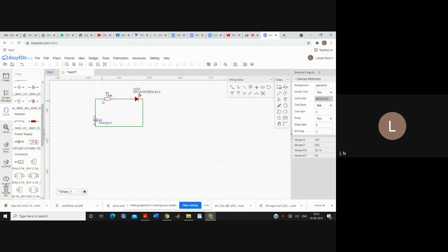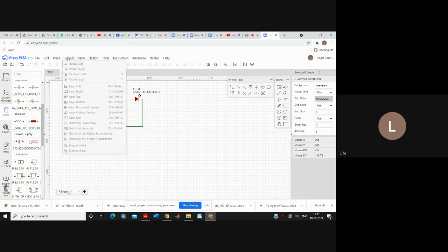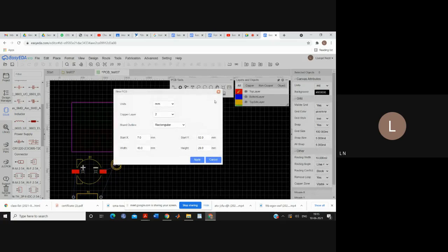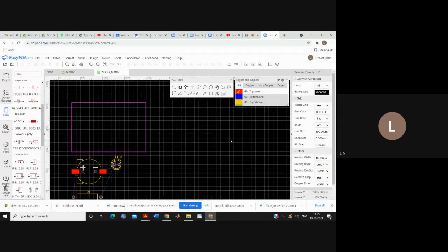All right. The summary of this discussion is, now I can create a three-dimensional view of this entire circuit very quickly. So I'll go for design. First of all, I will have to save it. Save the design, whatever changes you have done, whatever wiring you have connected, then convert schematic to PCB.